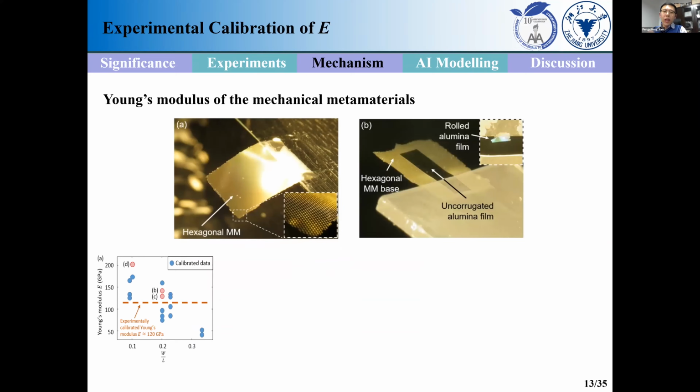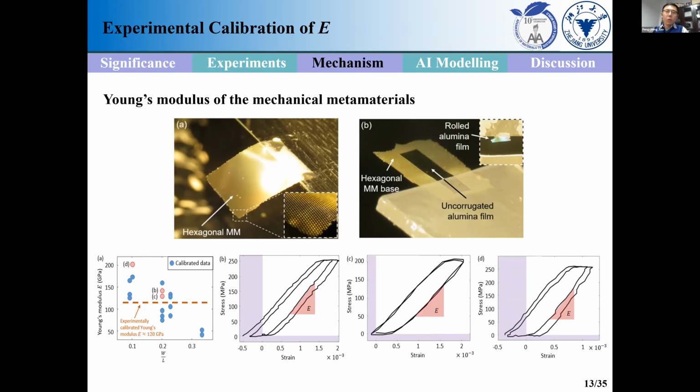Before really getting into the bending and tensile stiffnesses, we first want to test the Young's modulus of the material, aluminum, because we want to make sure that the Young's modulus is still maintained the same at the nanoscale. In other words, a scaling effect doesn't affect the Young's modulus of the material. And according to our experiments, our testing, yes, Young's modulus is maintained the same.